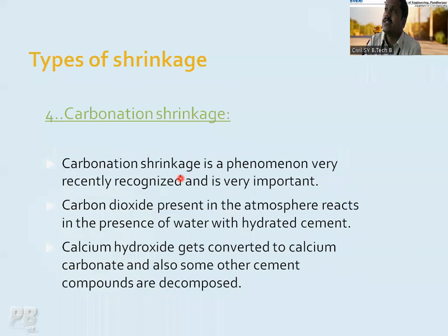So carbonation shrinkage is a phenomenon very recently recognized and is very important. Carbon dioxide present in the atmosphere, that is your CO2, reacts in the presence of water with the hydrated cement. So calcium hydroxide gets converted into calcium carbonate, and also some other cement compounds get decomposed during this reaction.